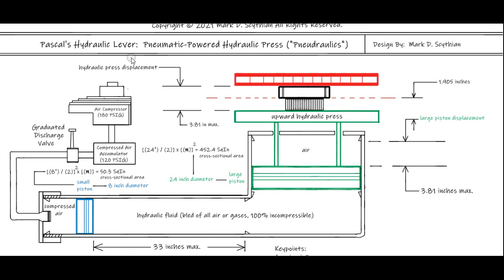So we see this with hydraulic jacks, hydraulic hoists in automotive garages, and the practical application is to apply compressed air pressure instead of something manual, so that some sort of a graduated valve or even a pumping valve with a check valve can assist the process of applying force to the input cylinder and conveniently result in output force at the large piston.